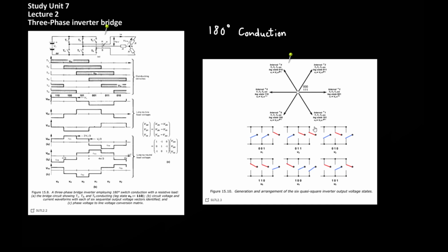So using this configuration, there is never a state where all the switches are closed or all the switches are open. So to summarize, each of these switch vectors will only allow for a single switch to switch at a time, and this reduces the stresses on these switches. There will never be a case where they're all open or closed.